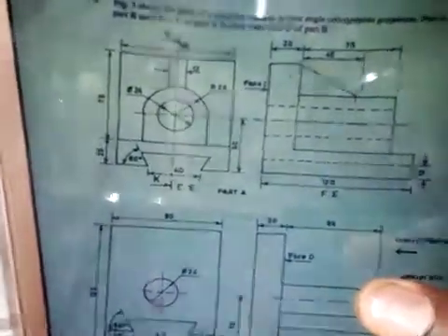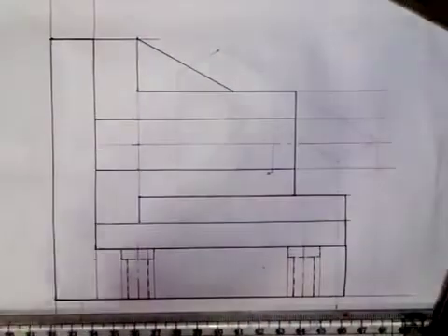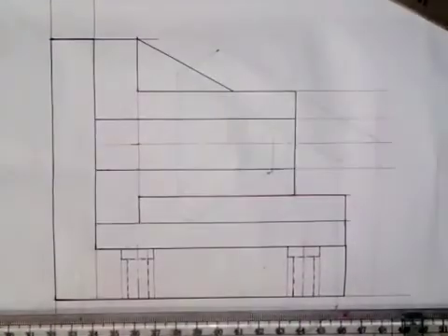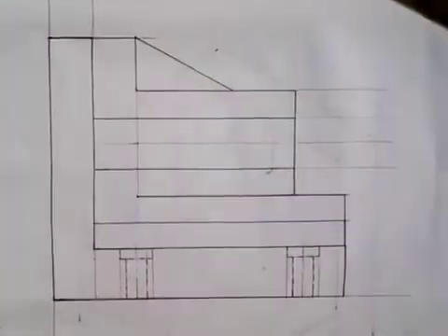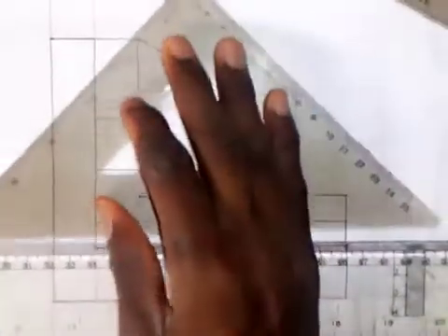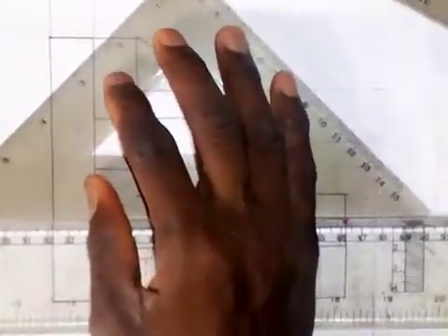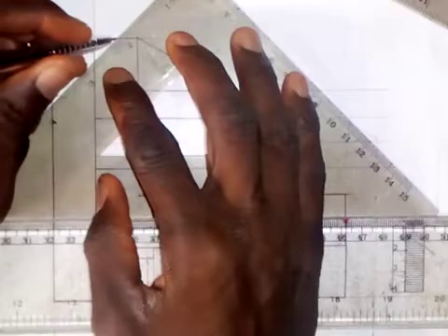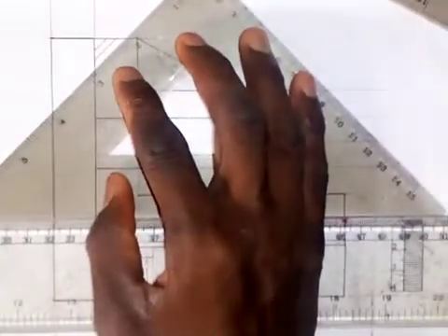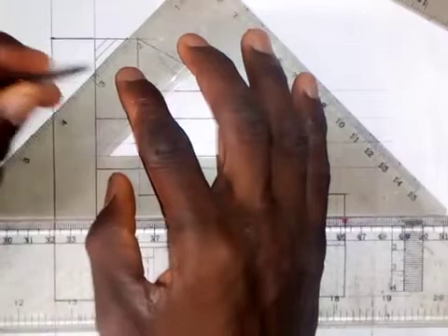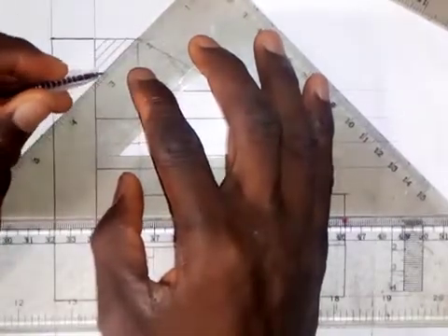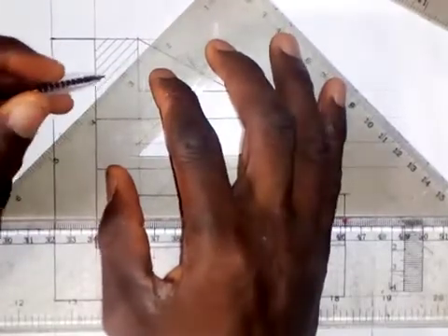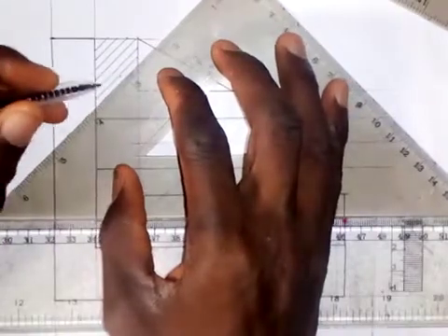So let's look at how the arching line is going to be. And then I need to remove this line that I drew here. It's not supposed to be there. All right, with our 45-degree set square, we arch this part now. Make sure the arching lines are equally spaced on this surface. You don't have to measure the space between them. Just use your eyes to do that.